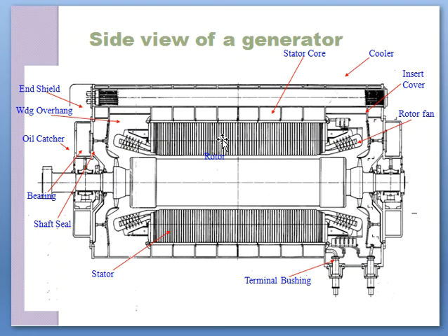All the windings are clubbed together in 3 terminals, because here we are getting the output voltage in 3 phases. So these 3 terminals, through the terminal bushings, the stator terminals are connected to the generator transformer, because the output voltage of the stator windings is not very large.